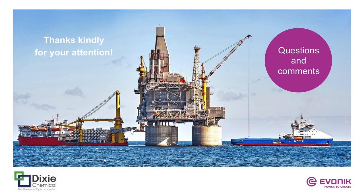We started off with a certain premise. We went in a couple different directions. I think we kind of came back at the end and tried to summarize as best we could where we've been with our program and where it is that we wish to go. So the complexity of these systems is now, I think, being brought to the forefront in terms of how the behavior can be influenced. Curative selection, curative blending clearly plays a role. Processing safeguards, understanding of microballoon selection, loading, safeguarding fracture, these things all come into play with regards to the end use, the performance of the syntactic foams in service.